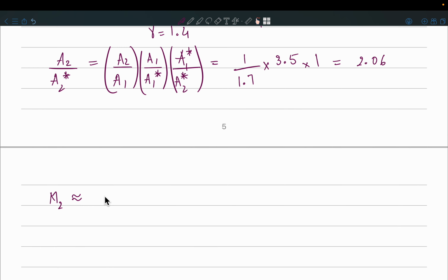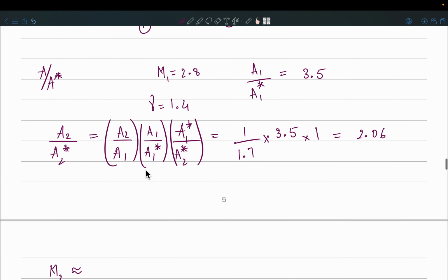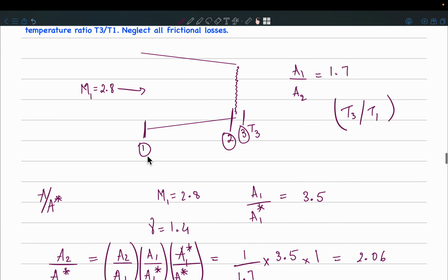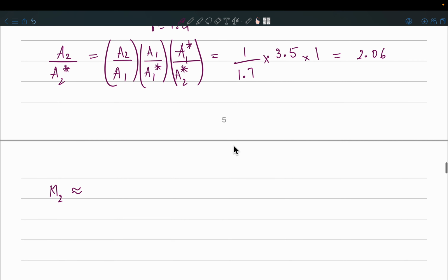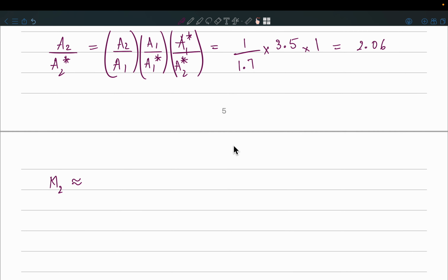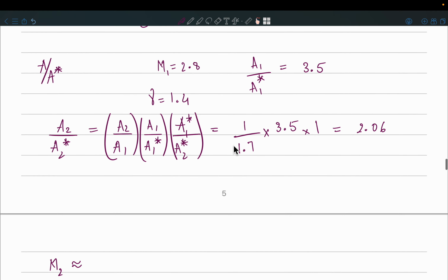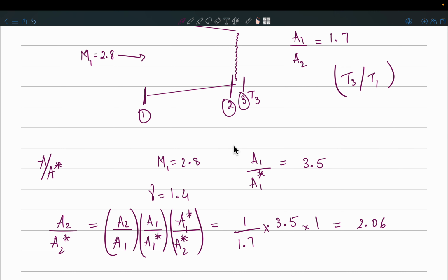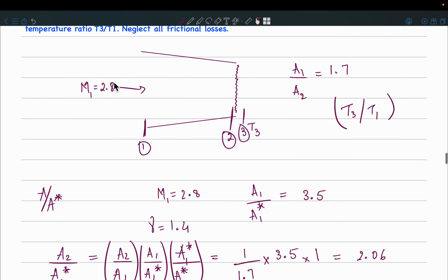Yeah, that is right. So, what was the problem? Okay, no. So, see, my M1, M2 is according to this question, station 1 and station 2. In the gas table, you will have one subsonic and one supersonic value. So, you should see the question. Now, here the flow was supersonic and it comes to section 2. It remains supersonic. That is why there is a shock.